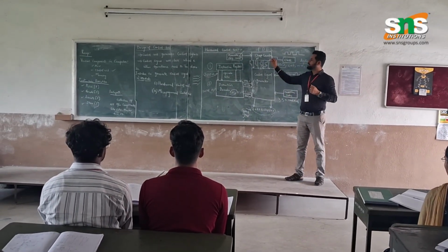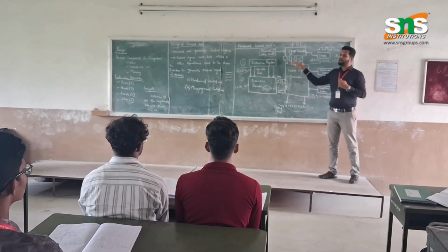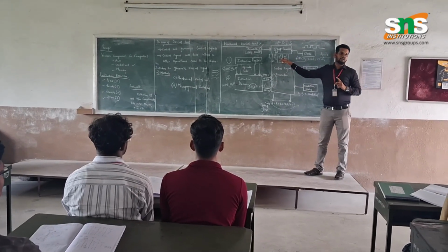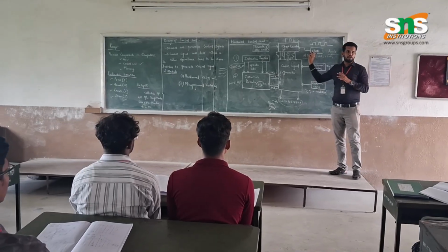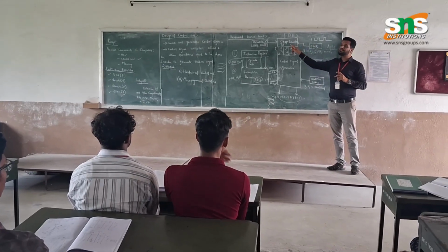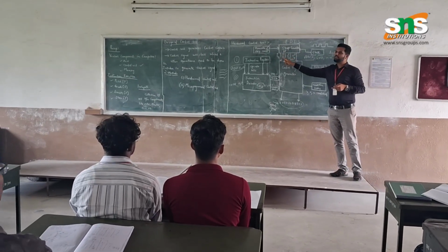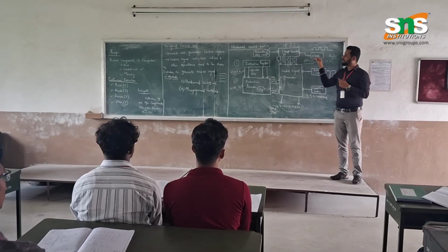Another block is the step counter. Every time, the computer does these four steps: fetch, decode, execute and store. The timing will be decided by the clock signal. The clock signal will synchronize all the operations executed by the step counter. The step counter is responsible for doing the fetch, decode, execute and store, but the timing is decided by the clock signal.